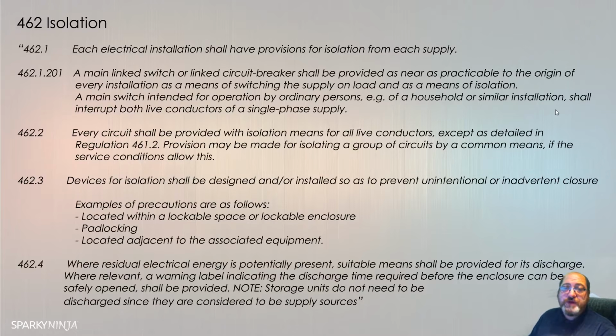So that's the safety requirements for the isolation. It's talking more about it having to be single pole only if it's not an ordinary person location, multi-pole if it is. It also says about it having to be lockable or in an enclosure that's locked, or literally on the equipment itself. Okay, and it also mentions residual energy. That's what we're talking about here about protection. Later on in 5.3, we'll also talk about identification and functionality and things like that.